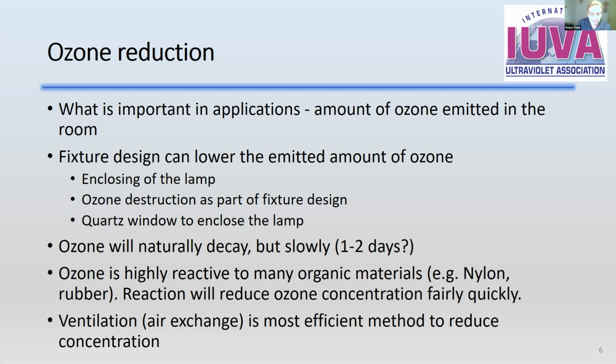In practical applications, ozone naturally decays, but fairly slowly. But one thing to remember, ozone is very highly reactive. So many organic materials react very quickly with ozone, especially nylon and rubber materials. And of course, that will eat up ozone.